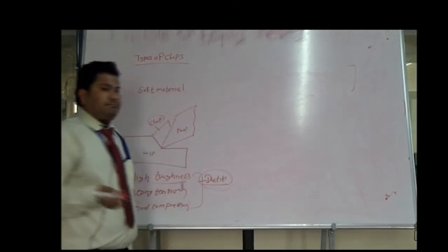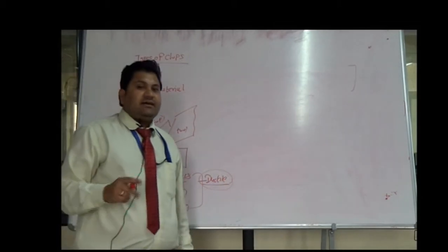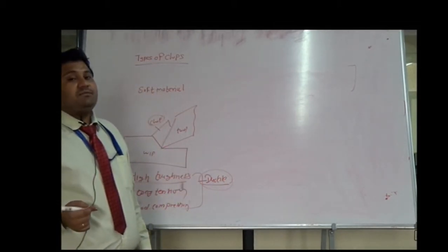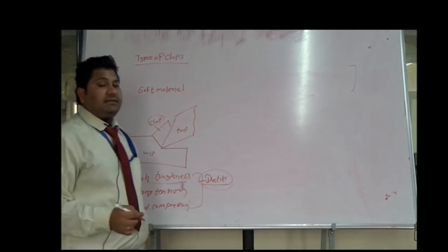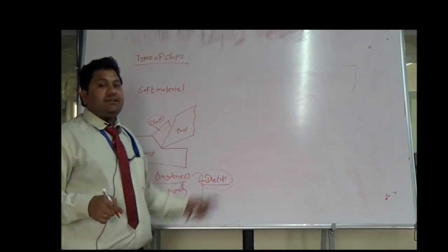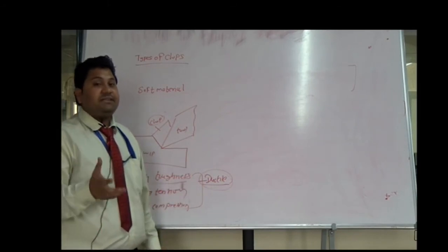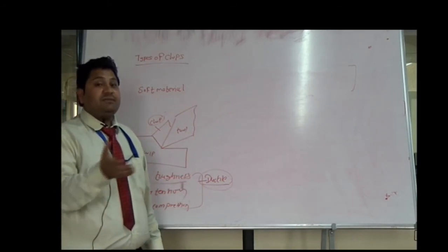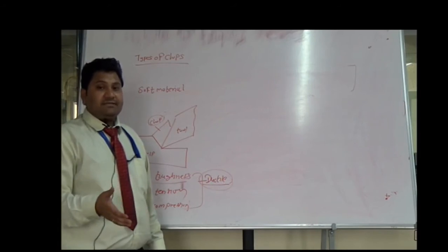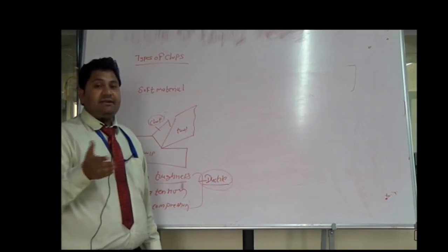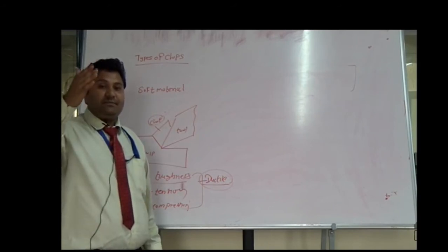Because of the mechanical properties of ductile materials, the chip will be formed in the form of continuous chips. The chip formed in the case of the soft material is continuous because of the property of toughness. Because of the toughness, the energy wave is absorbed by the material in the middle portion, and a continuous chip is formed.